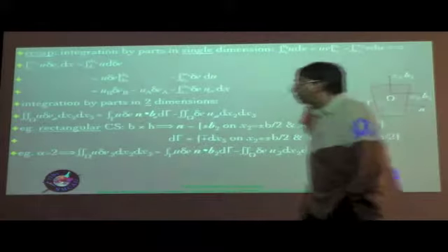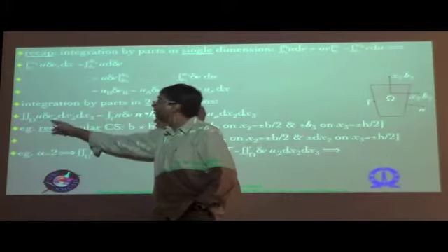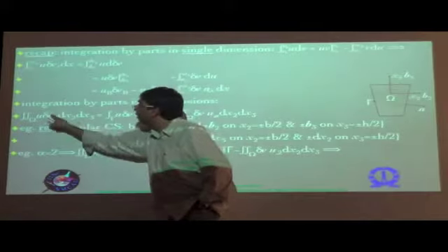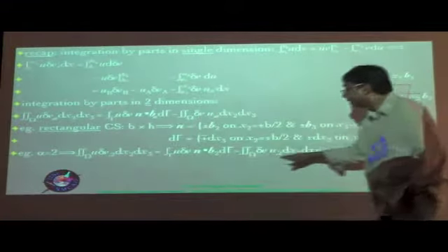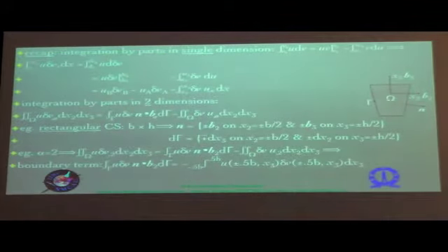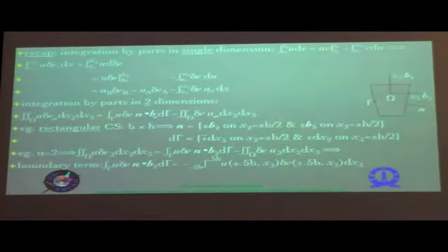Once you put that there, let's take an example where alpha can of course take 2 or 3 values. You can take it as x2, so basically derivatives with respect to x2 for the variational term. Once we substitute for those terms, you can see that this is what the integration would basically involve. It is not there on all the 4 edges; it just boils down to 2 edges for which there are non-zero contributions, and this is the boundary term.